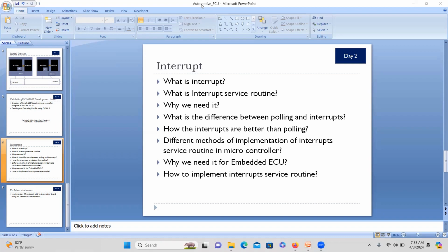In the natural flow of a program, you all know that a C program executes from main, because main is the starting point. After executing the steps we have in main, we have an infinite loop. In that loop, we continuously monitor events, checking whether that event happens. If it happens, we go and do a certain action. So there is no context switching and no program control transfer from main to some other service. It is just a continuous top-down flow of your embedded C program.